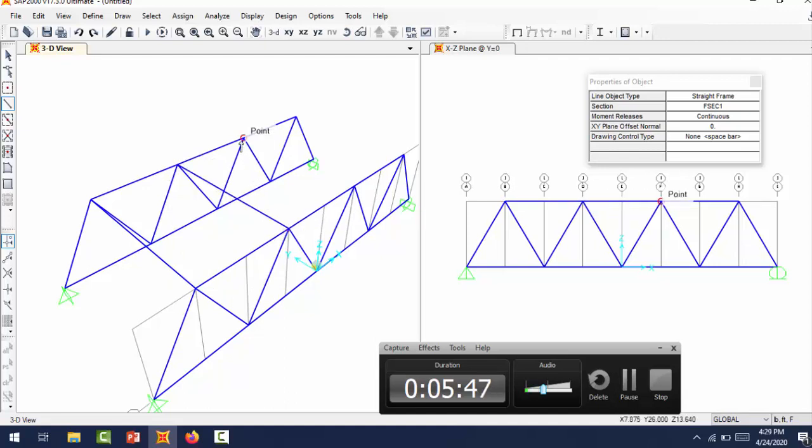Why do I do the right click? Because if I just click and keep clicking, you see it will follow me. I mean the cable will follow the movements of the cursor, and it will draw another cable on a position that I don't want. So let's go back. That's why you have to first click, second click, right click, which means I finish with the point where I wanted to draw the cable.